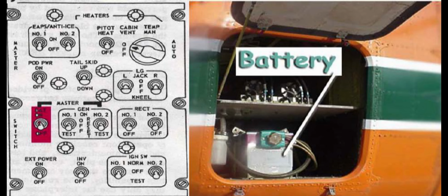The primary bus is powered by both converters when their switches are placed in a norm position, or by either converter should one fail. The primary bus is also powered by an external power source when connected, and the external power switch is in the on position. A monitored bus, which was initially designed to supply power to maintenance receptacles, has been disabled by EAC.